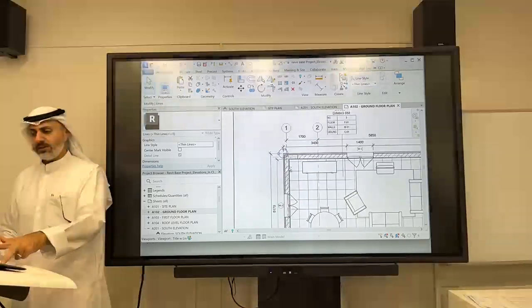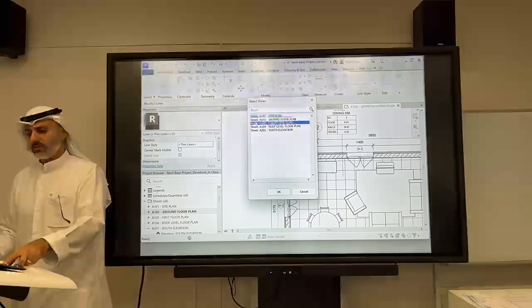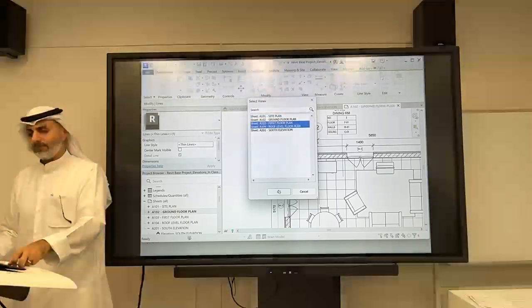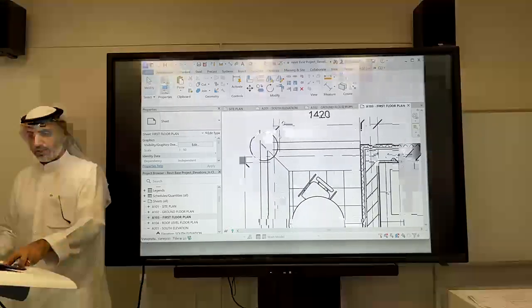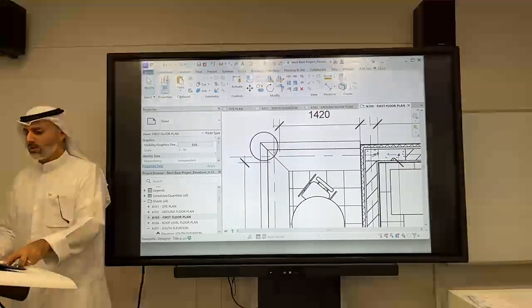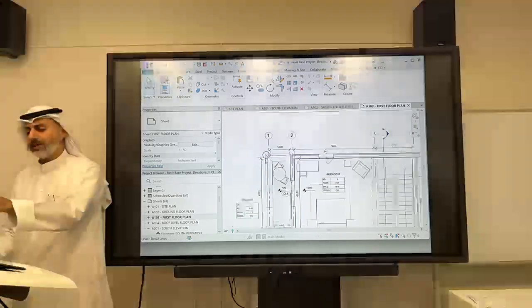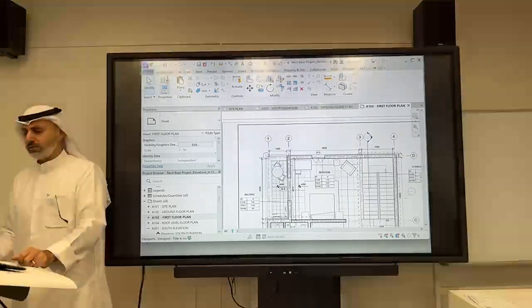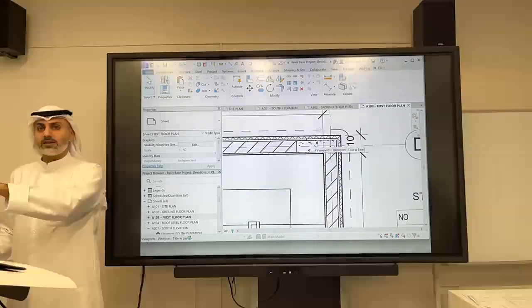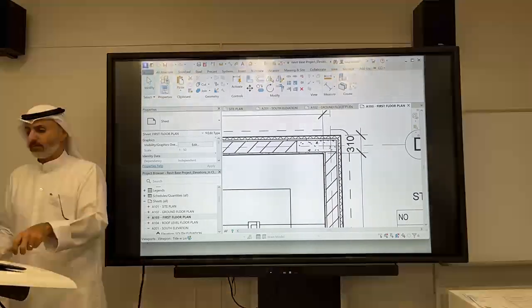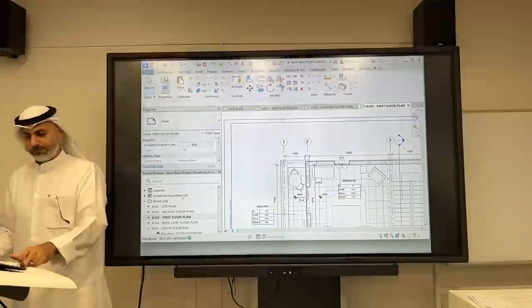So I do Control C, and again I paste it to, let's say, first and roof. So I got the first floor plan, I check, and it's the same corner. Let's find the corner, and then hey, this is a parapet, so I'm not really sure this is the corner or not. So try to find something that's, it could be actually better the corner of a grid. 4D, that's the grid that's not going to move. So that's a better reference. Let me do that.